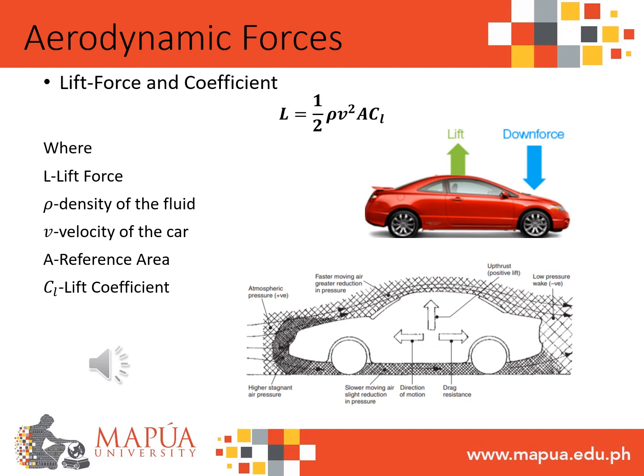When a lift is generated, it will act upon the center of pressure of the object and it will be induced perpendicular to the direction of the flow. In automobiles, the lift is generated when there is a pressure difference in the front end and at the rear end of the car. Lift force equation can be expressed as 1 half times density of the fluid times the velocity of the car squared times the reference area and times the lift coefficient.